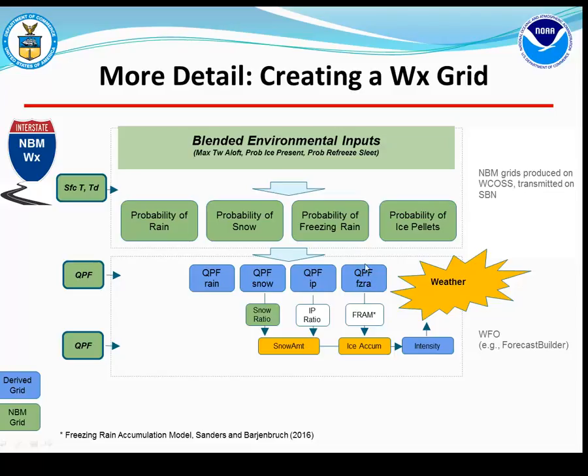And the same thing for freezing rain, where we used the freezing rain accumulation model by Sanders and Barjenbruch in 2016. We put the QPF for freezing rain through temperature and dew point analysis and come away with an ice accumulation.